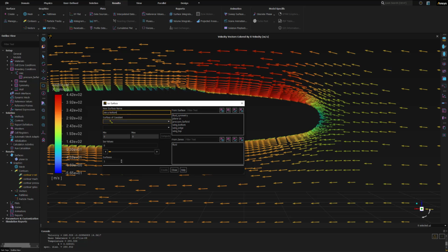Okay, and then here I need to select the mesh, and then I can go here and select the Y coordinate. So here, this green one is the Y coordinate. I will select here, and this isosurface is generated from the wing bottom surface.